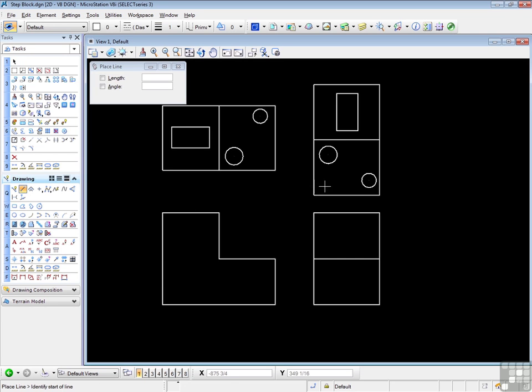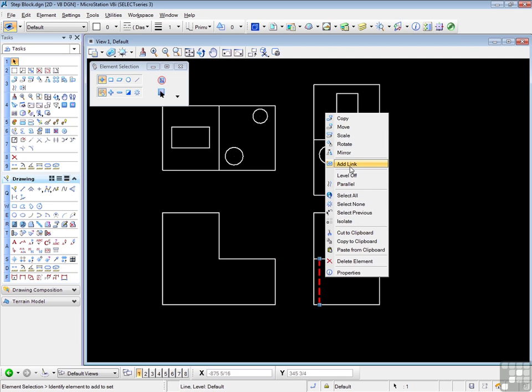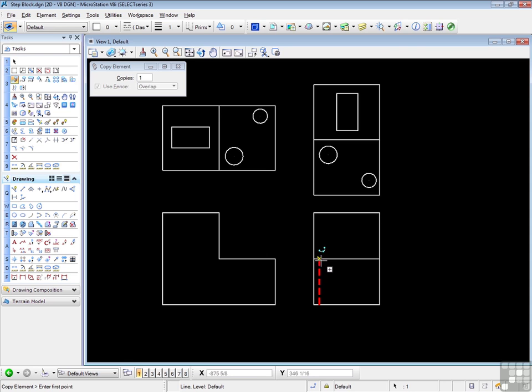Now it's easy to add hidden information. Start the line tool. Let's add the hidden lines for the circle. So F11 first, O key, drop down, enter, find my baseline there, drop down, enter, find the start point, and there. Let's add the remaining 3 of those. So do a copy. We'll start there, move along, enter, pick up that quadrant, move in this direction, enter, pick up that quadrant, and across this way, enter, pick up that quadrant.